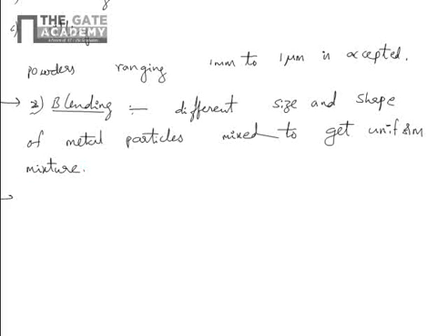After mixing comes compacting, which is nothing but compressing, applying pressure. As the pressure increases, the density increases, porosity decreases, and contact area increases.